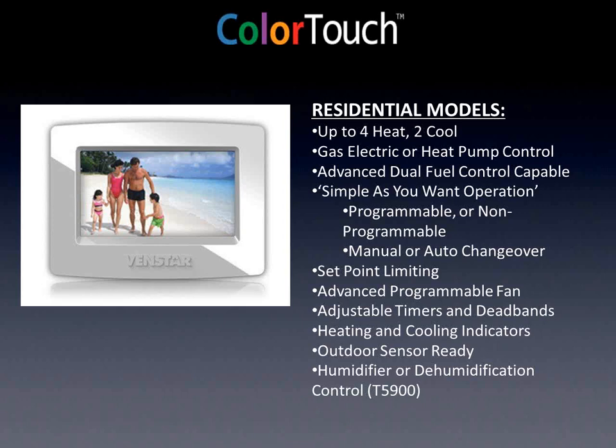If you got a gas system, it's 3 heat, 2 cool. It does do the dual fuel changeover, so you can put an outside air sensor on it and have it switch between your gas and your electric system. You can turn off the programmability. If someone doesn't want to program their stat, you can turn it off just like you can on a lot of these stats. Same with auto changeover. So there are some pretty cool things like that.